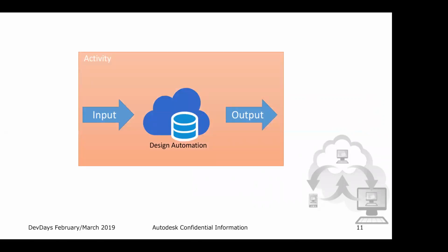Now, on the other sample, we used this app bundle, but we actually selected an activity to run. So the activity defines how it should be done. So I have the bundle with the code, but I have to specify what I need as input and output for that. From that sample, the activity defines that we have one input file, one input JSON with the data, which is the new width and height, and also defines the output for that job to run, and that's defined inside the activity. In this case, the app bundle contains the code, and the activity contains the specification.